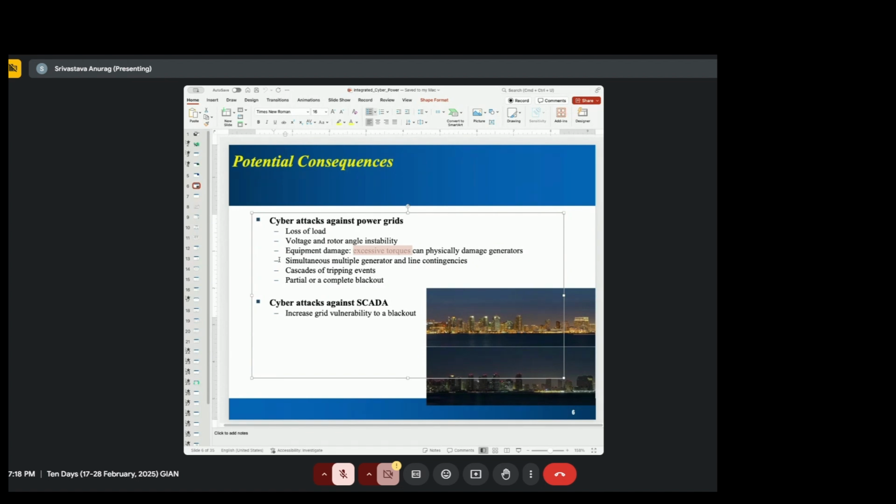In RTDS and in PowerWorld, there is also always a possibility to design your own user-defined model. Some of these will take several days or even a week to model just one generator, if you want to represent a user-defined model which is very different from what already exists. If it's a proprietary model, then you cannot do much about that.